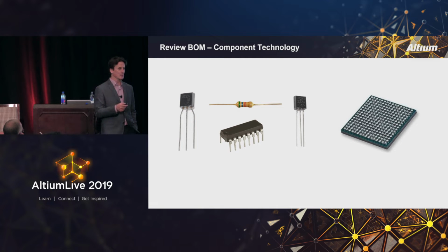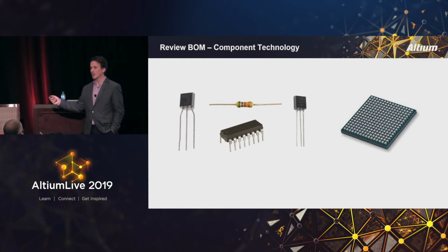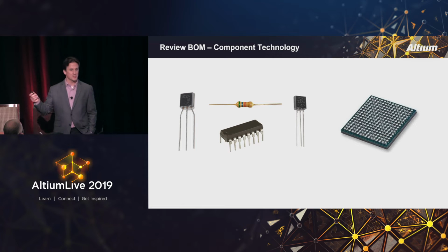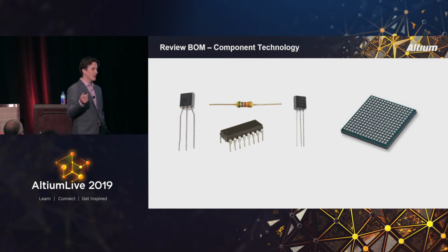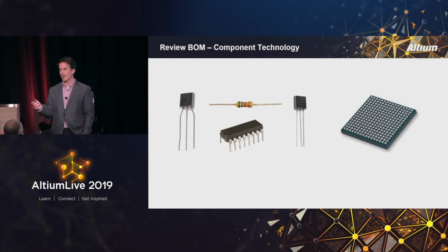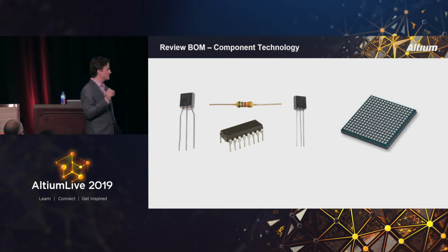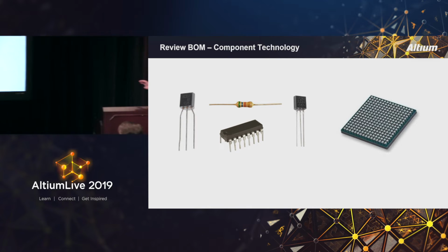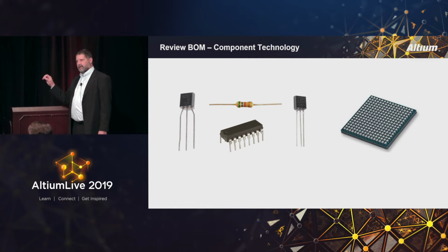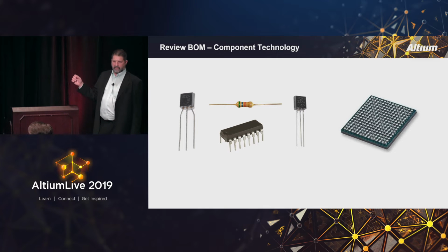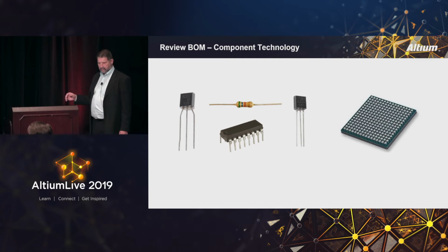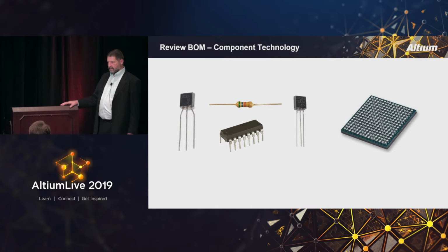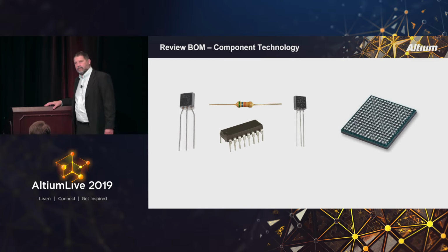And just because it might be half the size of the equivalent part in a higher pitch BGA, it is going to cost you a lot more money and potentially take up... Sometimes the lowest cost component isn't the right answer because it forces you to a higher cost board technology. Yeah. And every engineer should be doing that equation when they put a part like that on their schematic. They should know the ramifications of the PCB cost down the road.